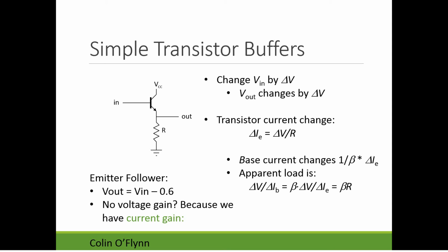So this is a very simple, effectively amplifier with a gain of 1. And we'll see there's a tiny bit of distortion and it's sensitive to what the input signal levels are, but the advantage is it just uses one transistor. So it can be very simple, especially if you just have an on-off signal you want to buffer or something like that, or you're not too worried about a very linear response.